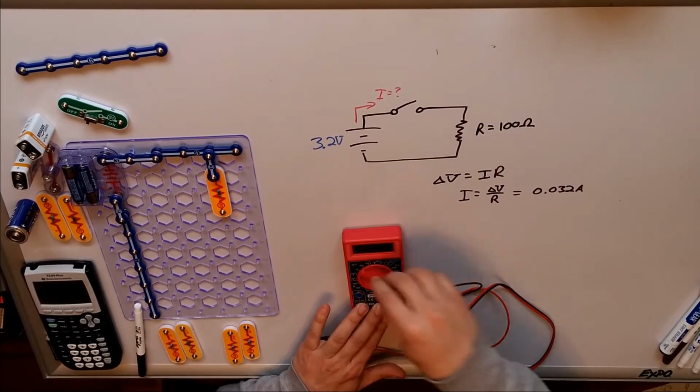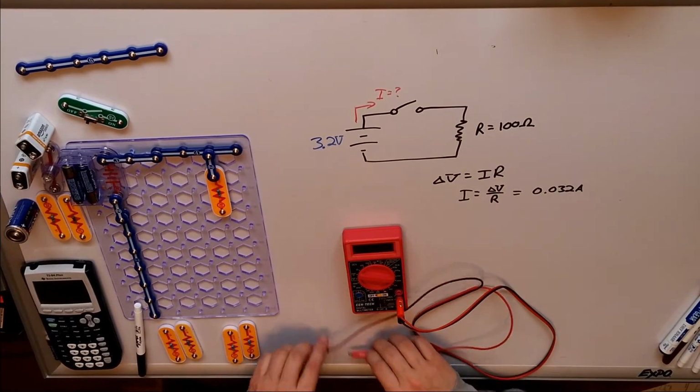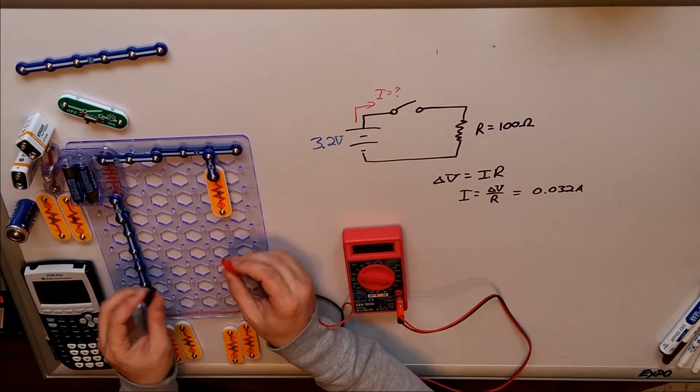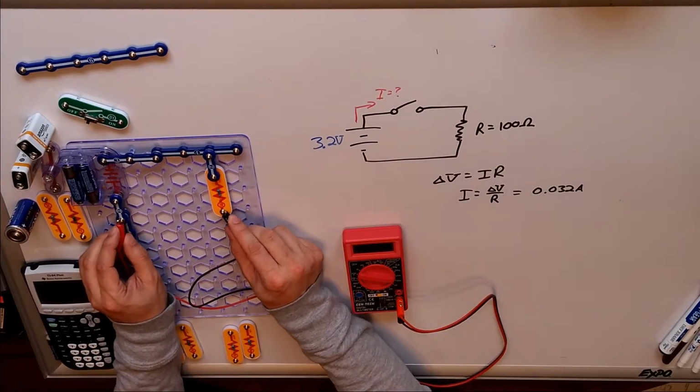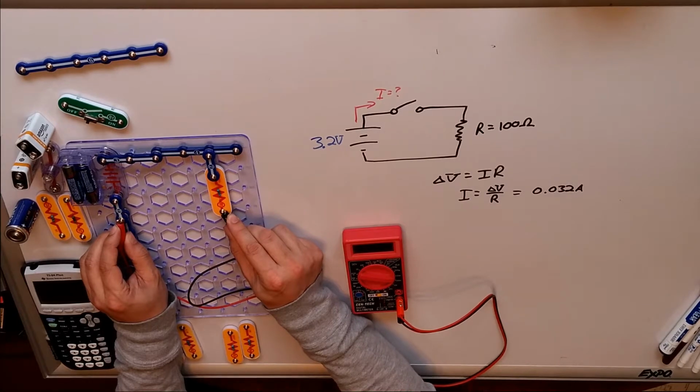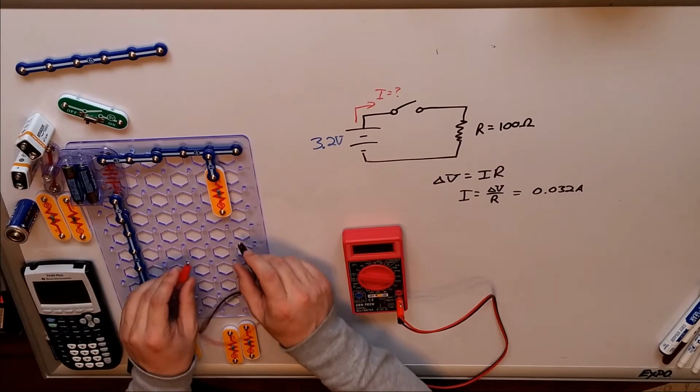So I retract my previous statement. This should be fine. I'm going to set it to milliamp, and here we go. I am going to set this up and get the following. I measure about 28.5, 28.6, so we're a little under 30 milliamp.